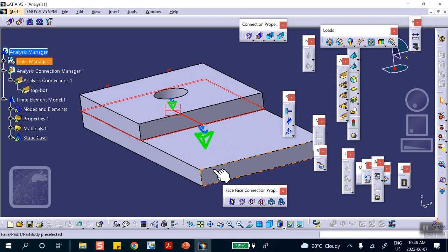Now, I don't want to model the bolt. And obviously, something is going to give in. Because if I don't model the bolt, the stress distribution is not going to be as accurate, possibly, as the bolt being modeled. I cannot see the stresses in the bolt because there is no bolt. Okay? So you create a virtual bolt so that it ties the two pieces together.